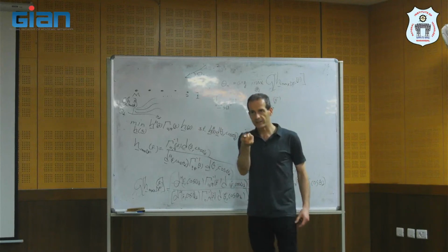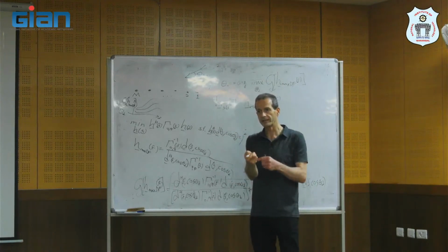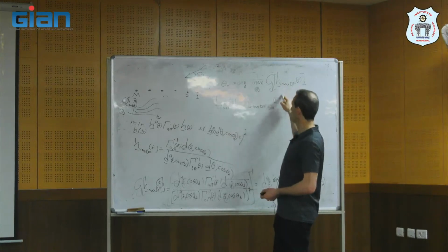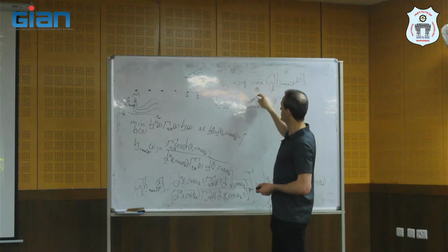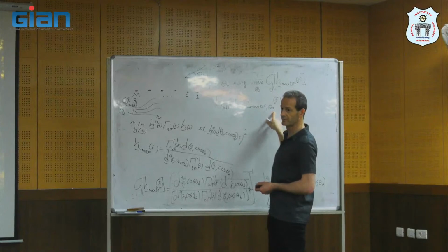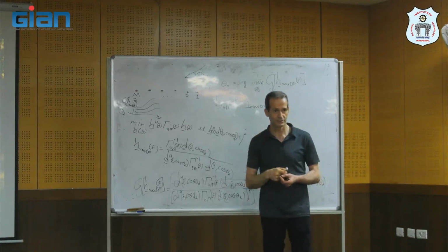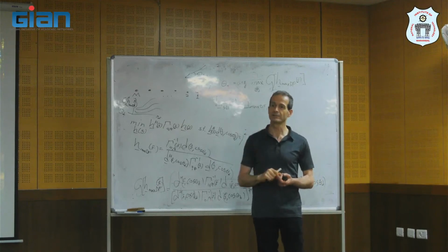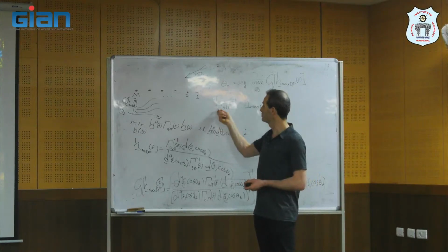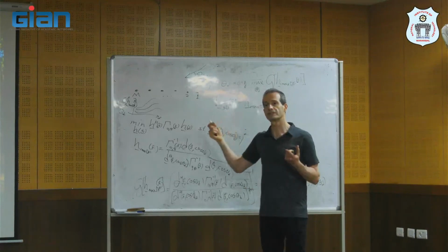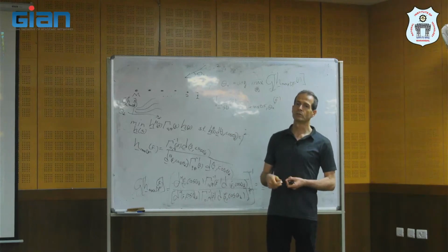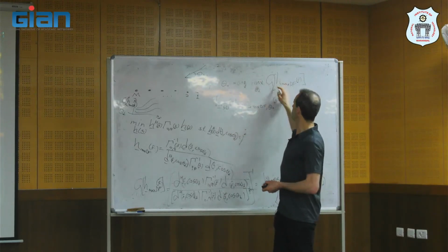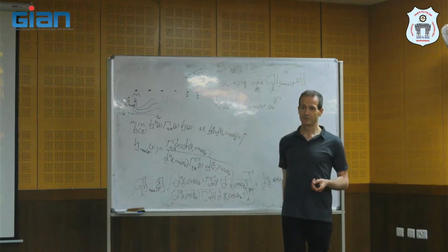And why do they direct it like this? Because this microphone array is designed with a fixed beamformer such that the maximum directivity factor is obtained for theta equals 0. So they direct it towards the source, which is very nice to understand, because they get superdirectivity. Superdirectivity means that we also control the steering of the array, and we obtain the maximum achievable directivity factor. Very nice.